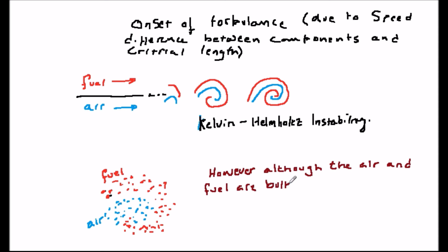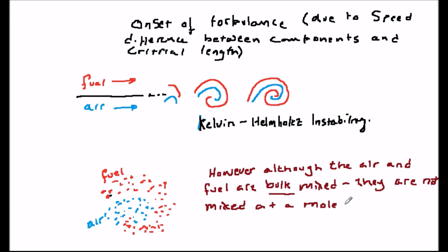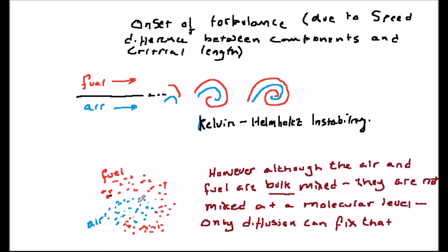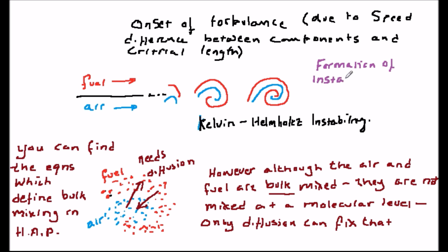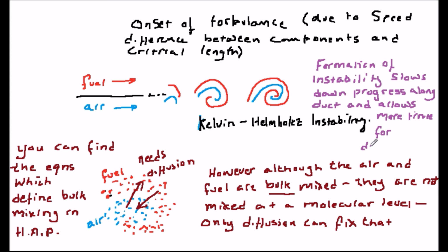On the downside, however, if the turbulence reaches the duct walls, it causes an increase in drag. And secondly, remember that the thrust is equal to m dot v. And if v_e is lessened by the appearance of turbulence, the thrust will correspondingly decrease. You can possibly see intuitively that this is likely to be the case. This is roughly equivalent to saying that the turbulence causes an increase in entropy of the flow. And as you might remember, we'd like our processes to be isentropic if possible, so that all the energy is contained within the flow and available for thrust.